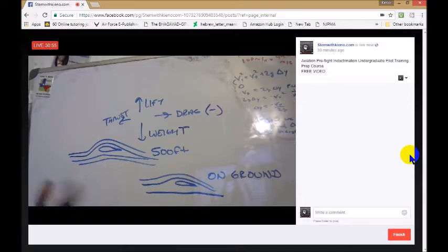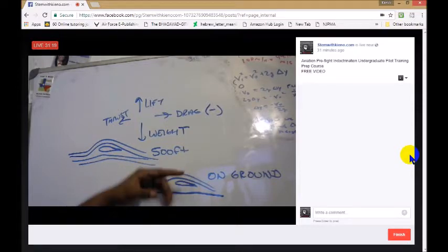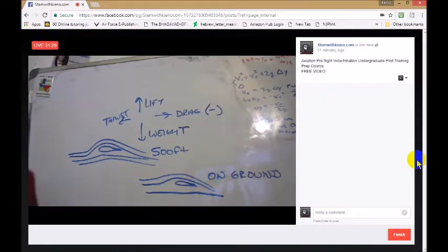As a flight instructor, on very, very hot, humid days when ground effect is more likely to occur, we train our students to stay within one wingspan, because this could really be happening on what we would call a short field takeoff, when we have a shorter runway that we need to take off from. So basically what we'll do is we'll break ground and we'll stay within one wingspan. Once we get our airspeed, then we'll climb out. So it's not anything to freak out about. We train and beat this into the students' heads.